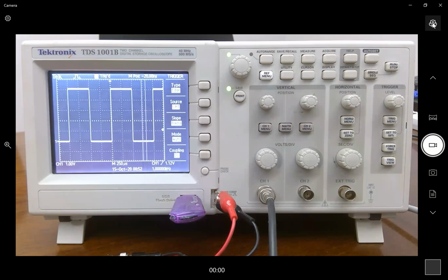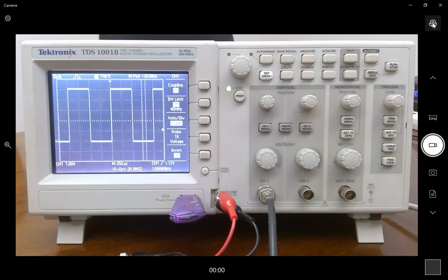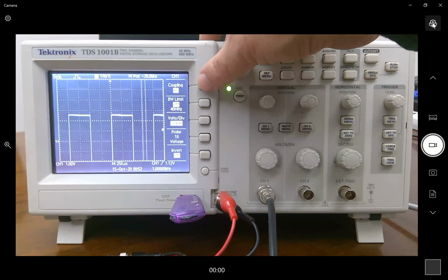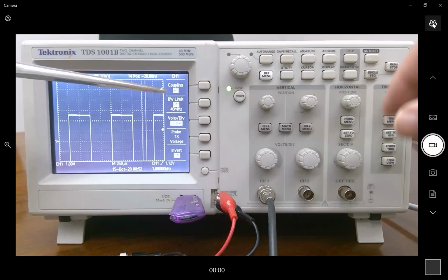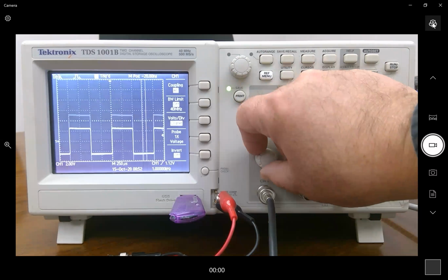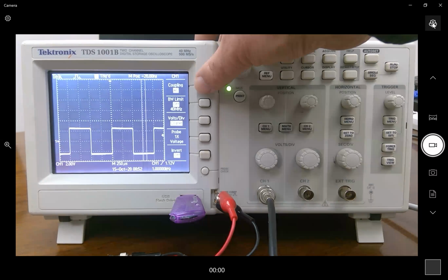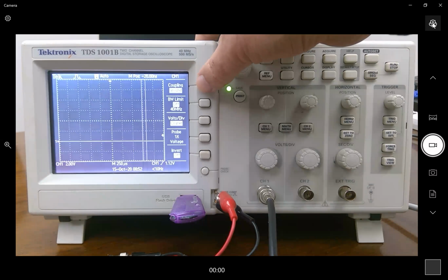So I'm going to turn on channel 1. And as you can see, you have DC coupling. I can scroll through this. AC basically moves the signal so that it gets rid of that DC offset. If I change it, you can see that the AC gets rid of that DC offset. You'll see there's also a bit of an incline now on the top and the bottom, because it's getting rid of that DC offset. If I then go to ground, the ground is good.